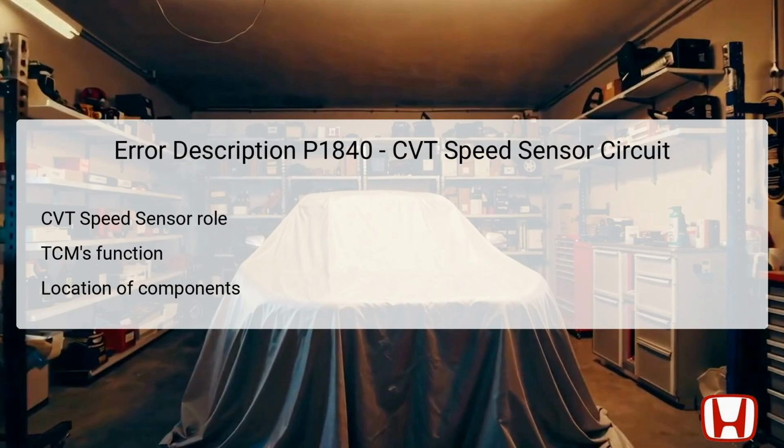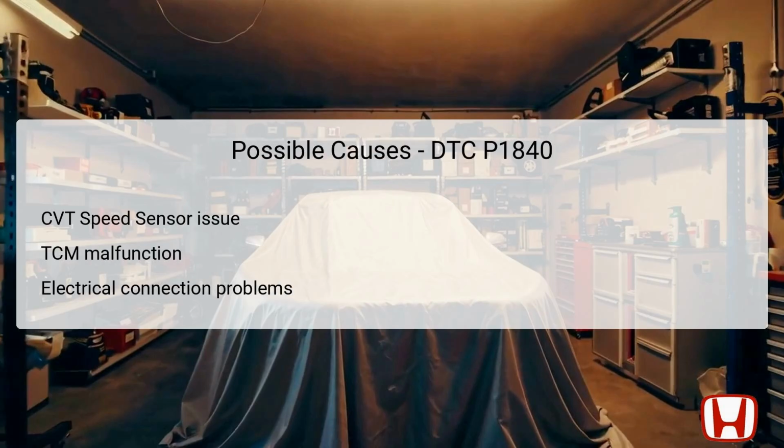If the measurements from the CVT speed sensor are inconsistent with the vehicle's actual speed, it can lead to suboptimal transmission performance, impacting throttle response and gear engagement. Understanding the roles of both these components and noting their locations within the vehicle are pivotal in effectively diagnosing and resolving DTC P1840.